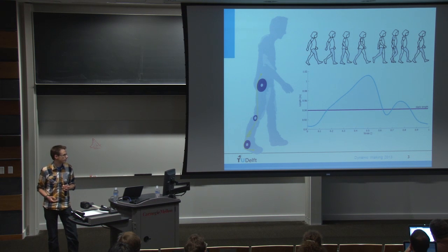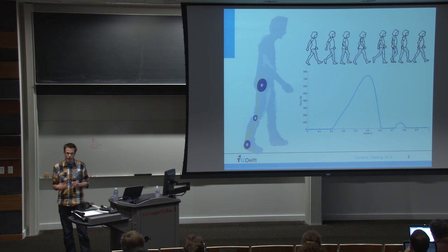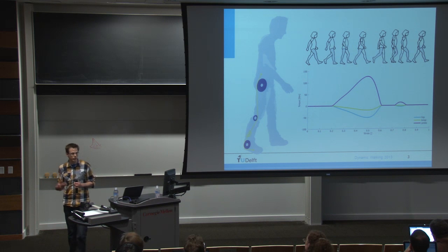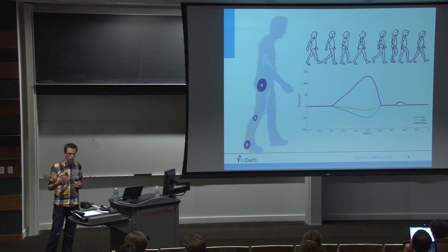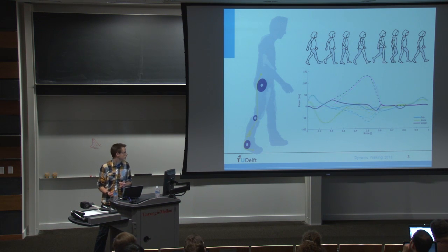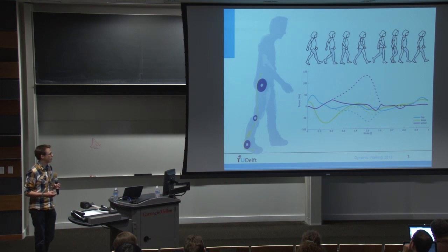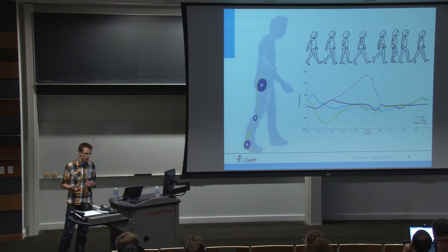At some points, this cable will be longer than its slack length, so there will be some force in the tendon. And we have this pulley, so this results in a moment around the different joints of the legs. If you optimize this, you can try to match these moments with the moments you normally observe in a gait pattern. So that's what you see here. You see that if you have this exotendon, you have a lower torque at the joints for the human, and we can interpret that as a more efficient gait.